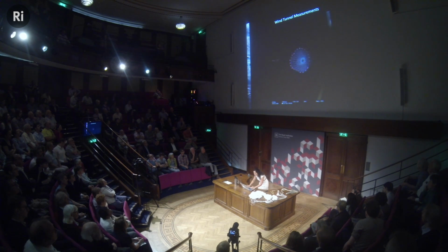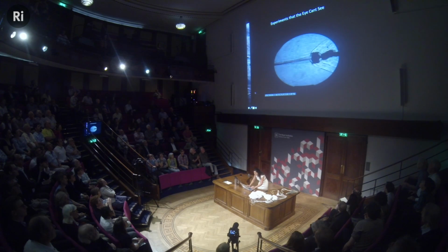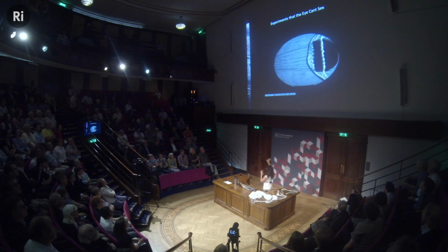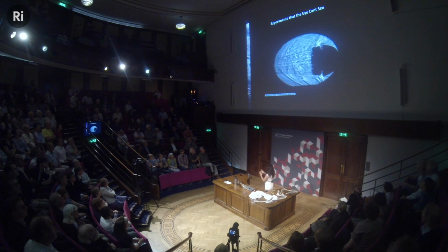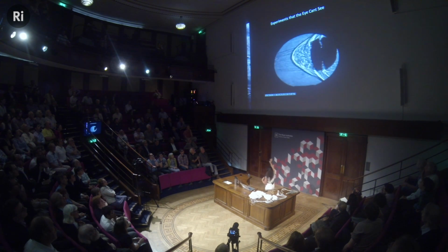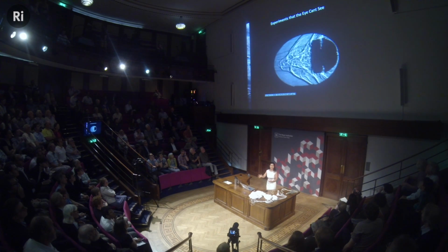And in terms of the fundamental physics of what's going on, we also used a technique called Schlieren, to take a look at what's going on in the supersonic flow field. And so the computer simulation I showed you before, you could see the bow shock moving back and forth. This technique allows you to see density contours in the air in the wind tunnel, and so you can see the bow shock is moving forward and it's collapsing, it's moving forward and it's collapsing. And so this is the physics behind what happens to parachutes in supersonic flow.